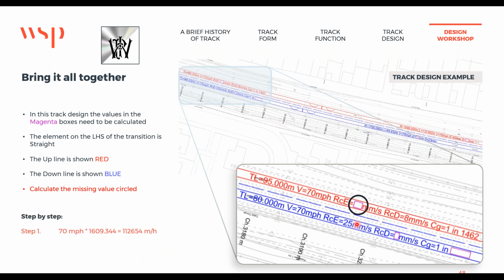Okay, step by step, a bit more involved this time. Let's get it down to, seen that one before, meters per hour. So remember the speed was 112.654 kilometers an hour. That's 112,654 meters per hour. Dead simple so far. Divide that by 3,600, the seconds in an hour, and that's 31.293 meters per second. The transition length is 95 meters long, and at that speed, where you're traveling 31.293 meters every second, it's going to take you 3.036 seconds to travel the 95 meters along the transition.